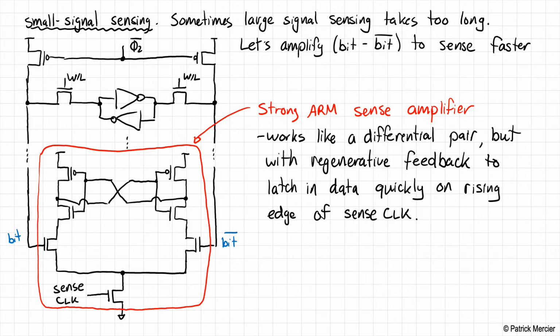As a result, the left inverter is going to be able to create its correct output value faster than the right inverter. And the outputs are differentially measured here, by the way. And then the positive feedback between these two back-to-back inverters really adds some extra gain into this amplifier and creates a very quick decision.